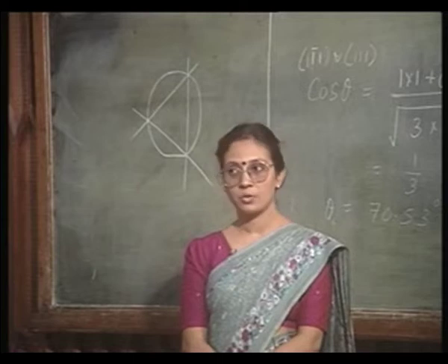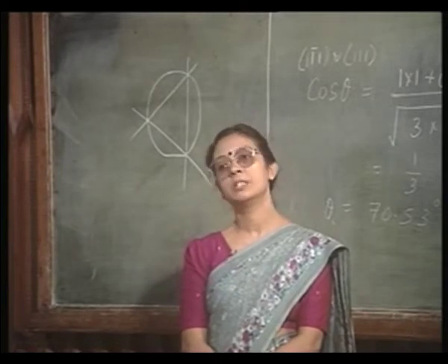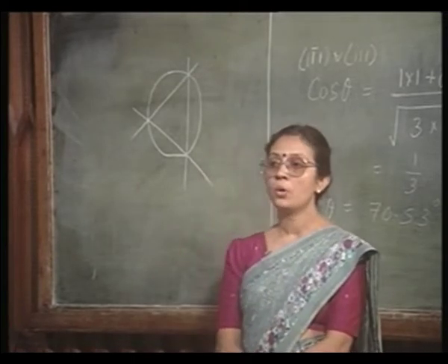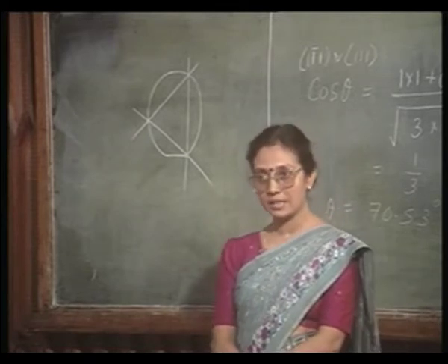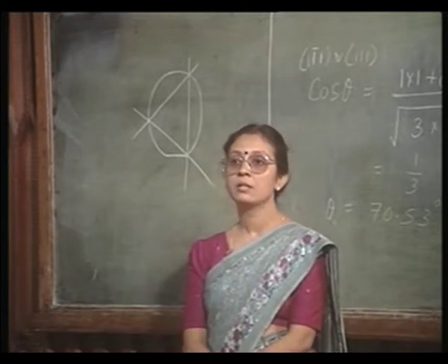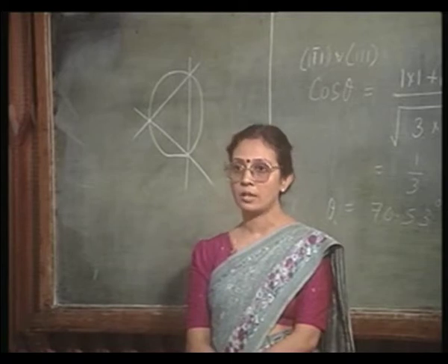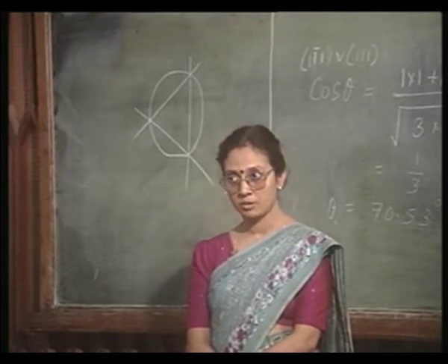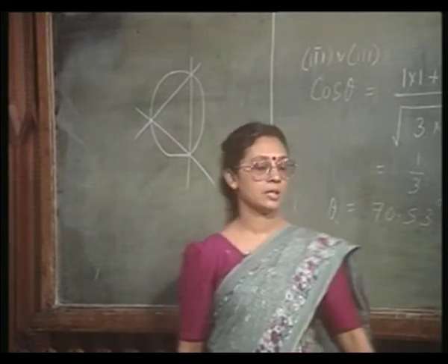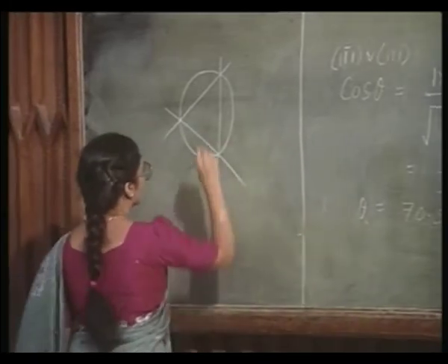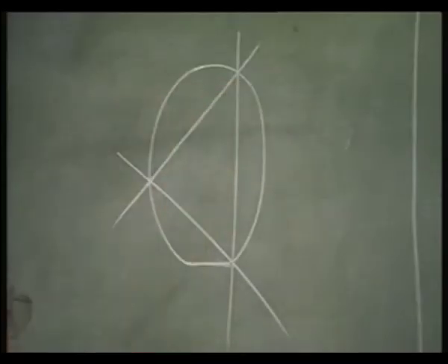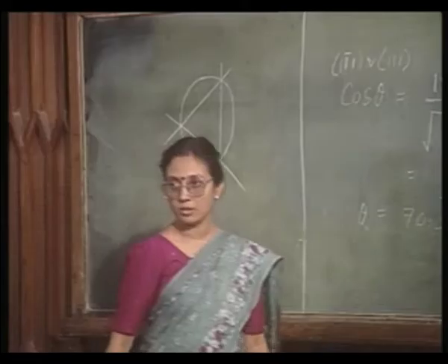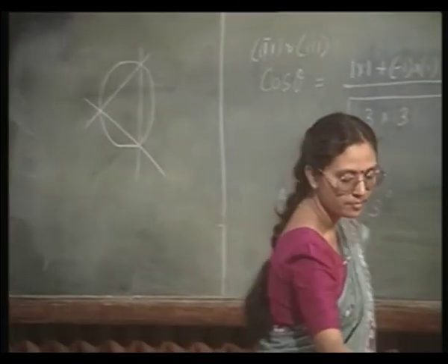So, you have a small problem here. What is that small problem? When I want to scribe silicon, I would like to get as many square or rectangular chips as possible. But in this particular case, you see, I cannot scribe in a mutually perpendicular direction. I will nevertheless try.